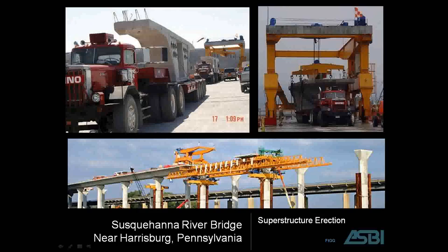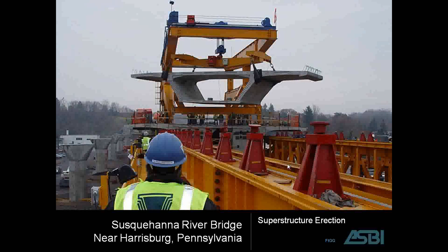This bridge was erected from above because the water depth of the river was quite shallow, and it did not facilitate the use of barges. Also, there are railroad tracks on this project, and this allowed the erection to occur above the railroad tracks without getting any crane locations down to disrupt the rail traffic. Here we see the segment loader rotating the segment and placing it on the underslung truss.